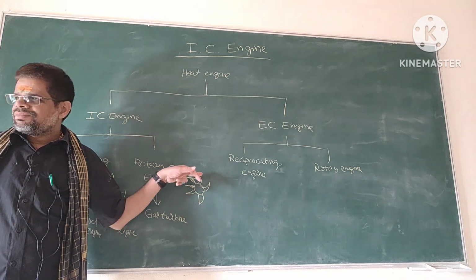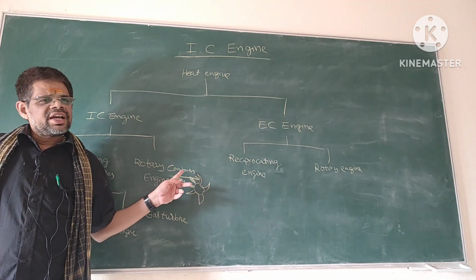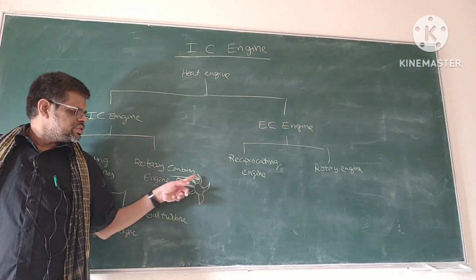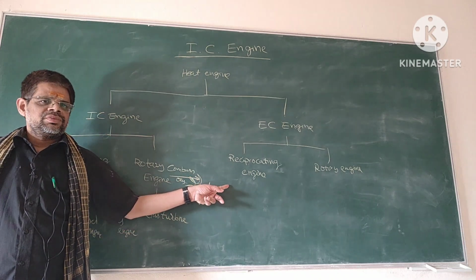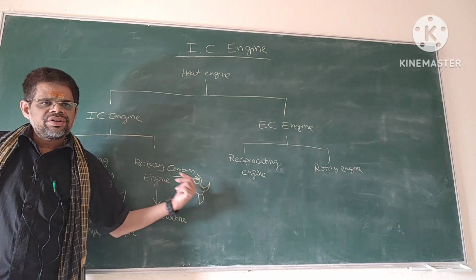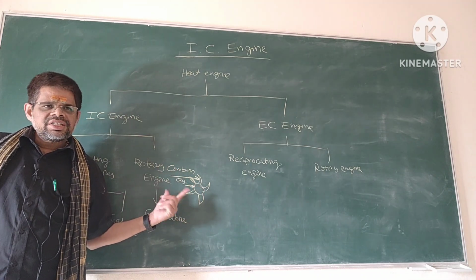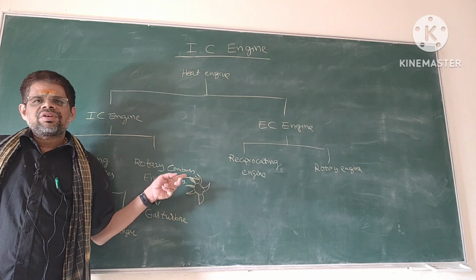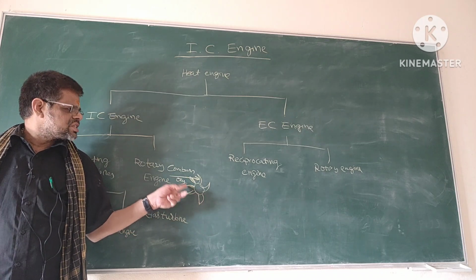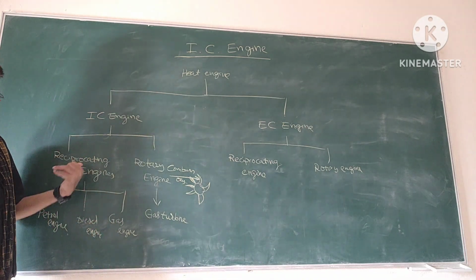Definitely it will rotate. So the combustion gases at high velocity are used to drive the rotor so that mechanical energy is produced. Here also the heat energy is converted into mechanical energy, but are there any reciprocating components here? No. Simply there is a rotor, which is a rotary component. That's why this is called a rotary type of internal combustion engine.